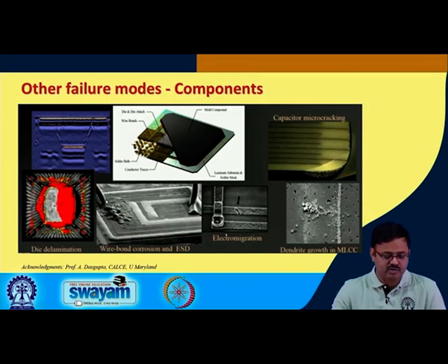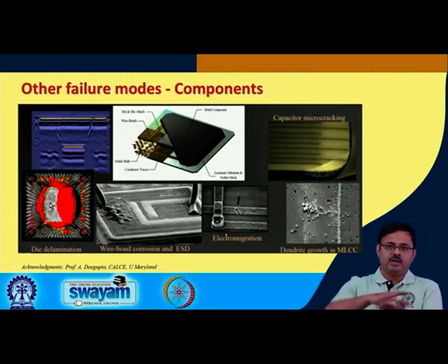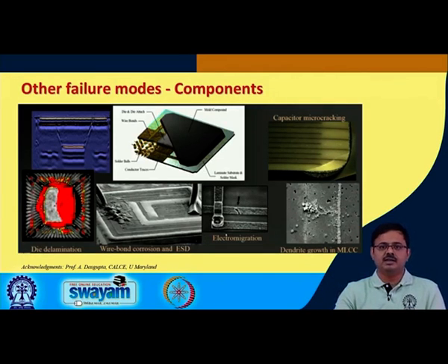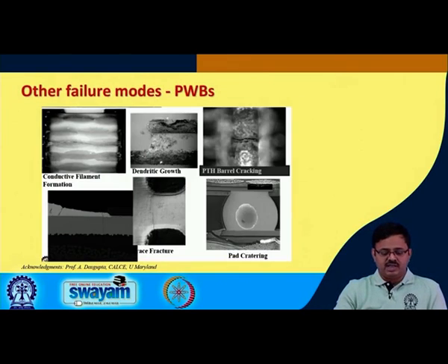You see the wire bonds have corroded over here, probably due to moisture, due to some other chemicals or gases, corrosive environment. Die delamination, at a certain point it has delaminated from the substrate, possible, right. Solder joint delamination is possible. Another thing, let us look into the next one.